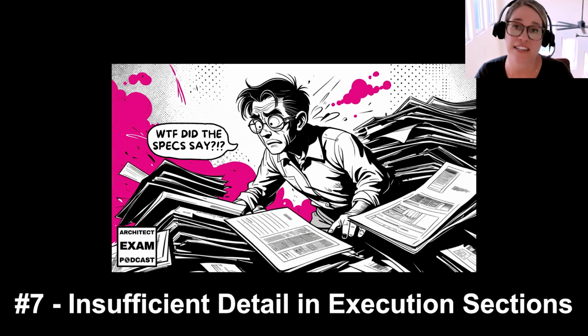Many architects focus on the products themselves, but they end up using vague language and vague guidance on how it's installed. I've definitely done this. I've specified systems before. One time it was a waterproofing system that was below grade, and I was vague on the language, on how the surface should have been prepared and how the flashing should have been completed. And what ended up happening was, after our project was complete, we had water infiltration on the lowest level. And this is something that could have definitely been prevented if I had very clearly written execution language in the specifications.